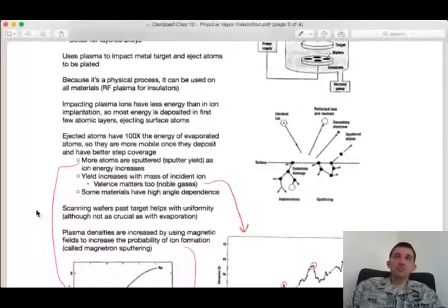Remember, the whole reason we didn't want to heat it up when we developed rapid thermal processing is that every time you heat up the surface, you give energy available for diffusion, right? So you go to a lot of trouble to put dopant atoms just where you want them, and you want to minimize the amount of time and the number of times that you heat up your wafer and start to move those around.